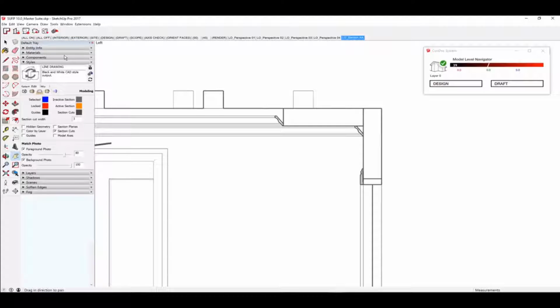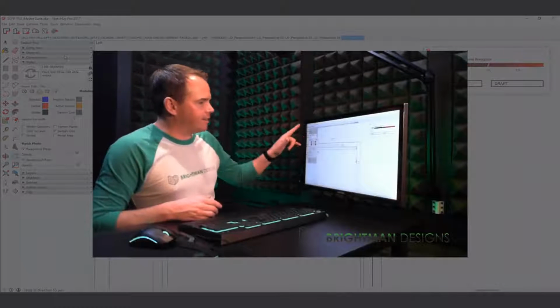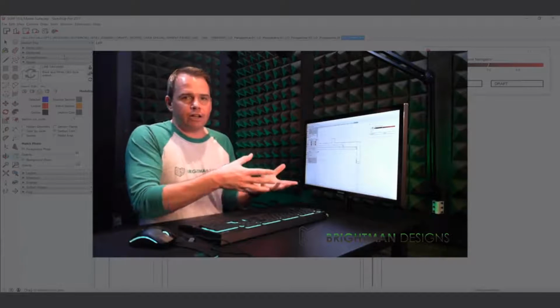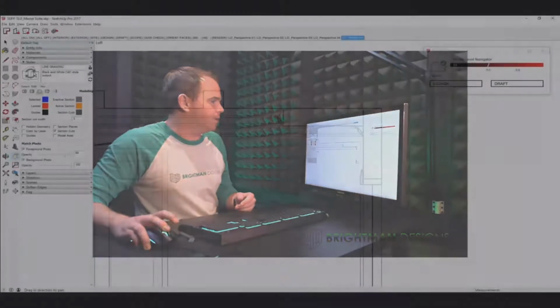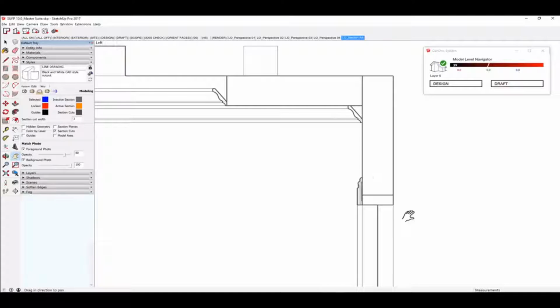Now notice that when I change the properties of a style, I get this warning sign that this style needs to be updated. All right, so if I want to save this change, I do need to click on this thumbnail, and that is now going to remember that my section cuts are dark gray.